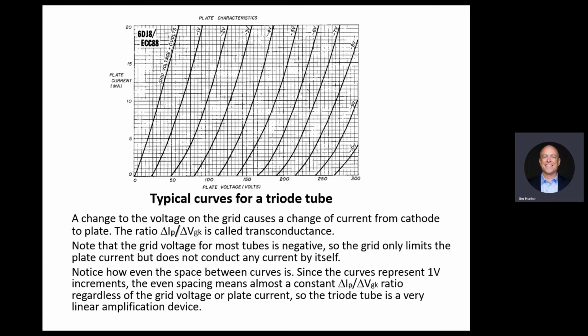Another thing we're looking at on the curve is how do we know how to bias, where to put the tube where our signal is 5 millivolts? I mean, should we put it at 0 volts and let it swing?